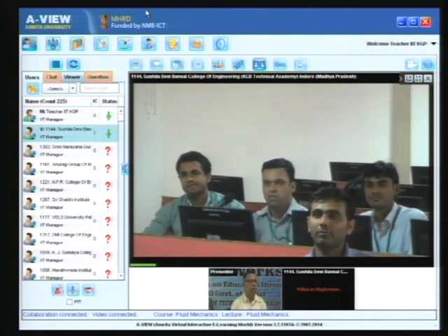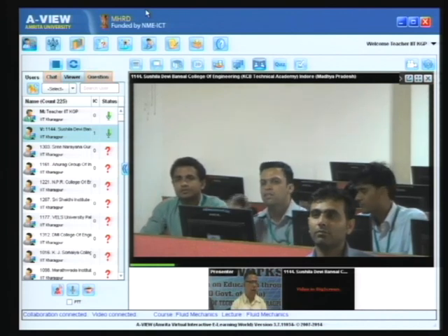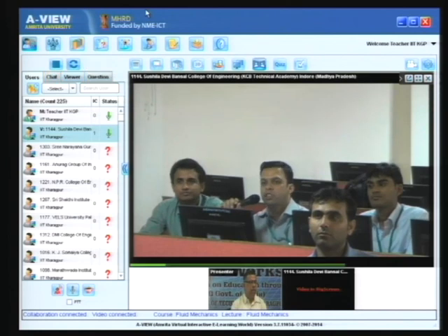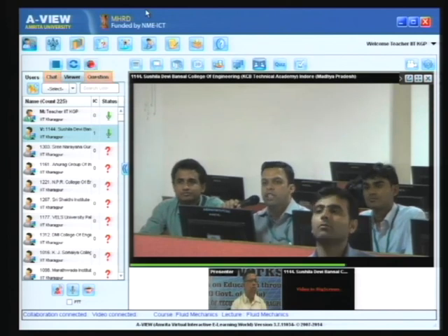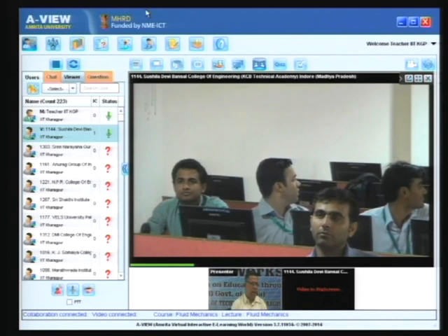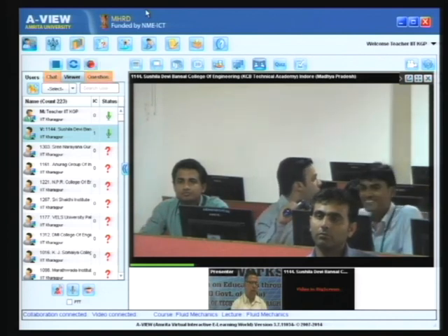See, in the case of gases, it is due to molecular motion. With increase in temperature, the molecular activity increases, and exchange of momentum between layers increases. In the case of liquid, it is due to cohesive forces. It is not directly proportional. Who has given you this idea? Directly proportional means mu is equal to A plus Bt. It does not increase like that.